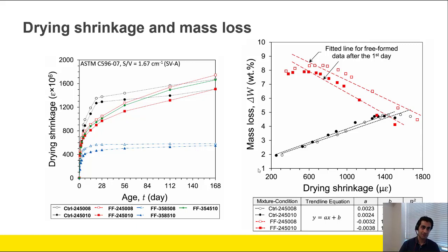because we have a lot of unhydrated material inside the sample, so some of that can happen based on getting moisture from the environment and hydration. And also we've seen that carbonation is happening, and that carbonation also provides extra water for hydration to happen. So some element of carbonation shrinkage is also there. This result we need to study more, but it provides some interesting outputs in terms of what's happening when we're looking at free-form shrinkage.